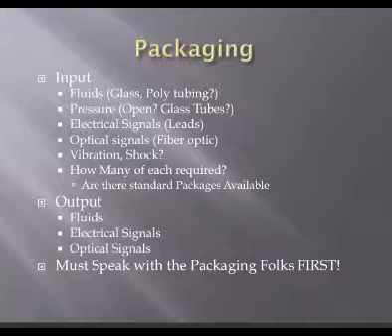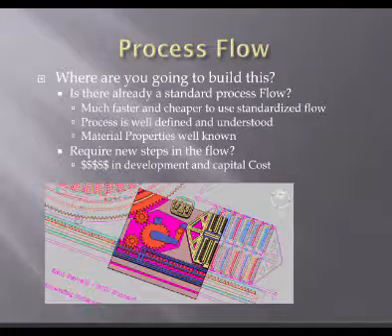I mean, they would have connections in the middle of the chip. So you'd have to put a wire from the middle of the chip over all this other stuff. You know how most packages are and most computer chips are? The packaging's on the edges of the chip, right? Especially in MEMS devices, the modern packages are flip chip. So you get an array of gold bumps on one side, and then they flip the chip upside down and they package it that way. But the packaging guys know their stuff. So if you're starting from scratch, it's probably a good idea to figure out where this thing's going to go and how it's going to be packaged.